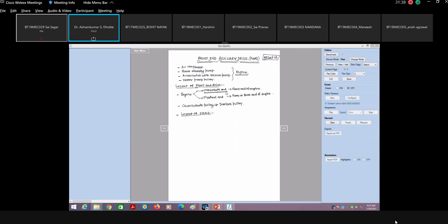So now this crankshaft has one ring which is used as a dampener for damping out the vibrations which are produced due to the firing of the engine. Because in the engine there is a sudden explosion or burning of the fuel, and during the power stroke a number of vibrations are produced, and some of them get transmitted to the crankshaft, which have to be damped, because otherwise the complete engine will vibrate.